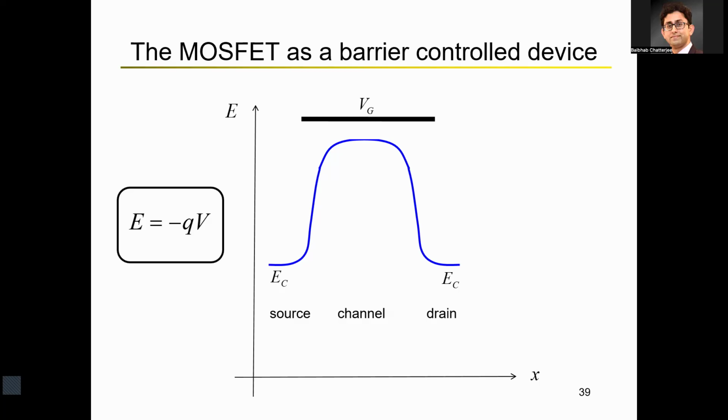Now, of course, the source and drain already have a large number of electrons. If you have a region in between which also has a large number of electrons, you can assume that as a continuous region of N-type silicon, right? And that's how we form the channel, and that's how the conduction occurs from source to drain in terms of the majority carriers. You also looked at the energy band diagram representation of how we can explain it from the point of view of device physics.